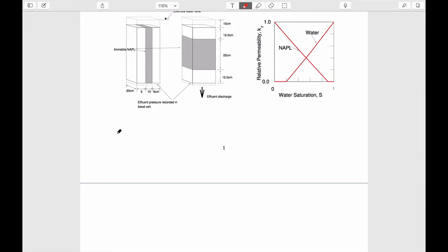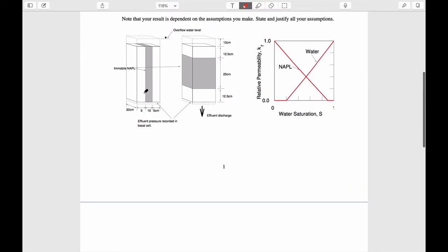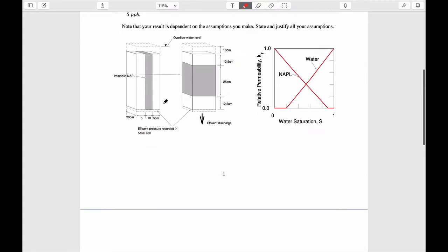The crux of this question, you don't have to read it, you can read it if you wish, is to figure out exactly what the rates are that water will flow through this sample if you set it up as basically a flow test. So you have a sample that is constricted on 4 sides so that the flow will occur through it. The flow is driven by this supernatant fluid on top of it, which saturates the whole sample.